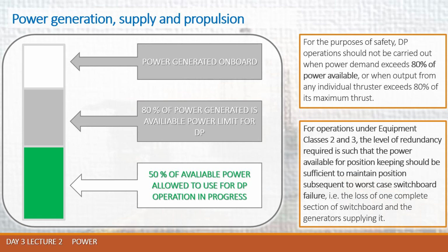Start next standby genset if load is above 85% on thrusters for more than 30 minutes. Start next standby genset if load is above 93% for more than 10 minutes. Or start next standby genset immediately if load reaches 105%, or if we are overloaded by 5%. But this is something about Kongsberg.